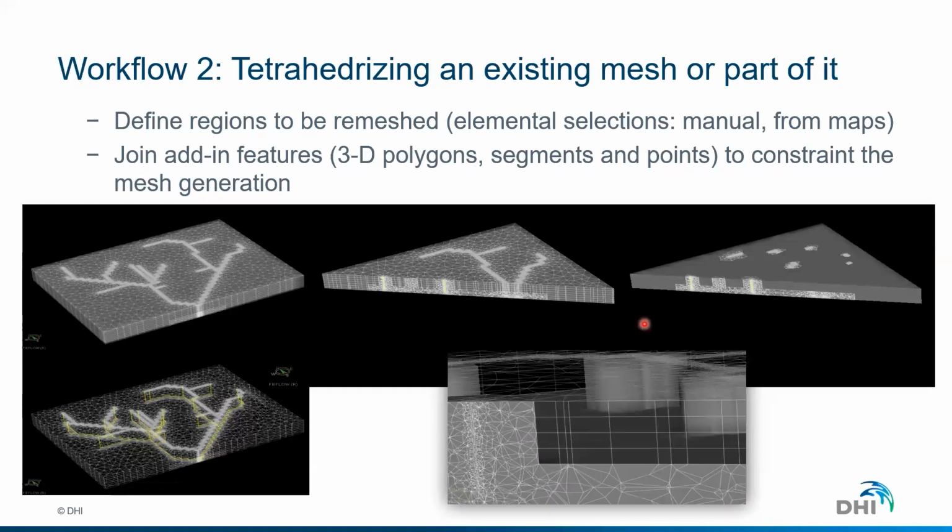And this is very practical, and is not much done. So that's what I would like to emphasize in the webinar, although the technology is not new. It is very practical to introduce new geometries that were not previously in the model. So if you have a well-defined system of lines, this could be a set of dewatering pipes, or anything, you can take this part of the volume, and FEFLOW will remesh the volume and then connect the new to the old one as it was before.